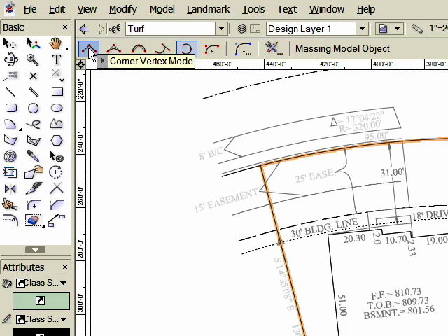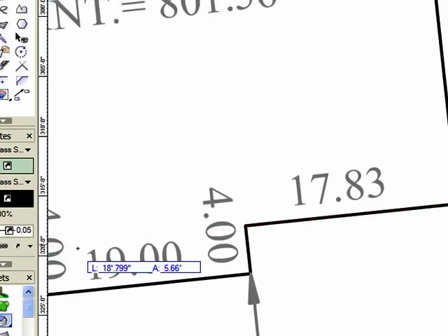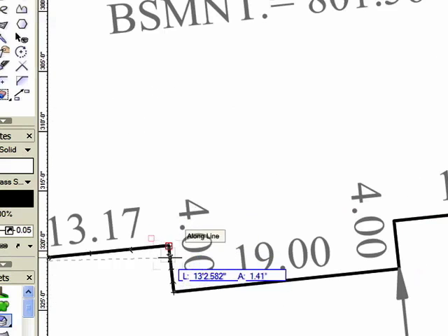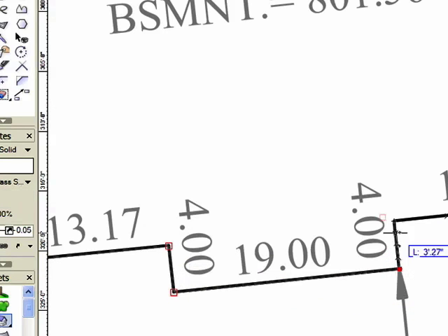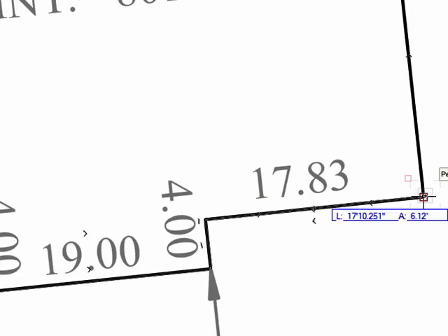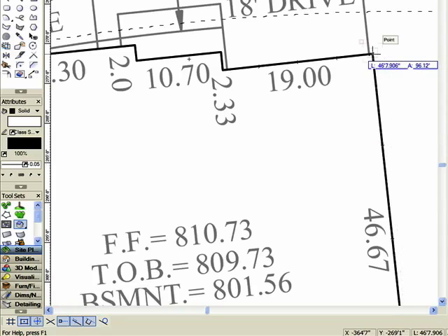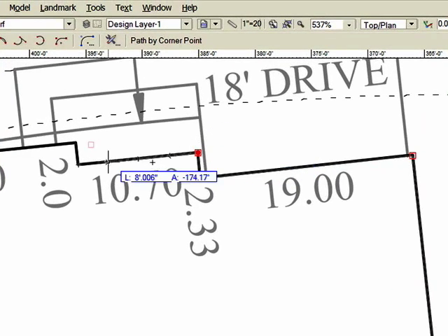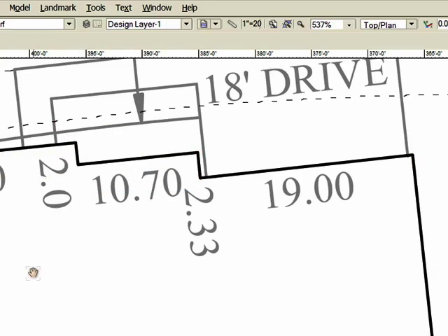So in this case, it again is operating off the polyline modes, and those polyline modes, as I'm tracing, give me an advantage of trying to be as accurate as I can with the straight sides, or with the straight edges. And as I continue around this building, I'll note that with the dimensions that are shown on this building, I could have tabbed in those dimensions if I had this in an orthogonal relationship, horizontal to my working plane. I could have worked from that angle and tabbed those dimensions in as well.